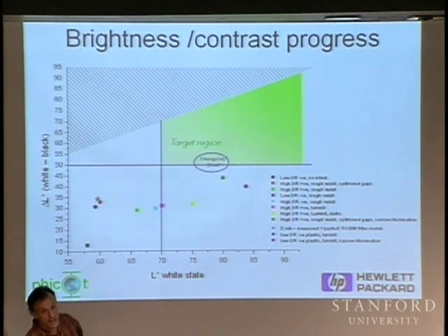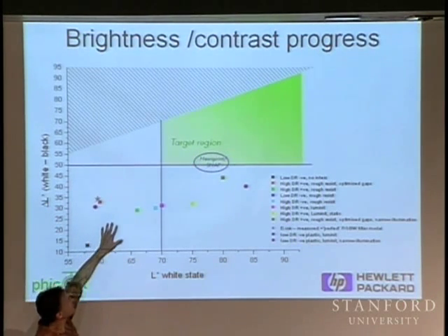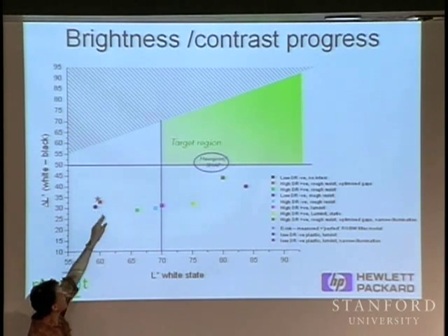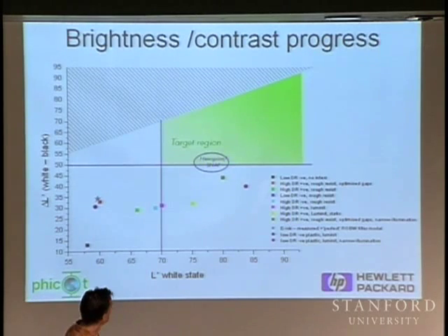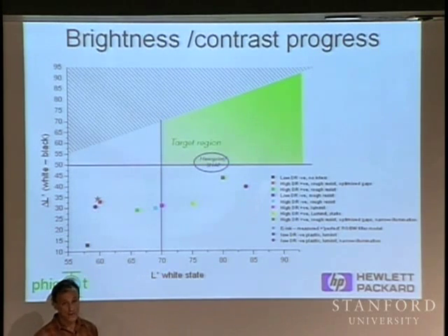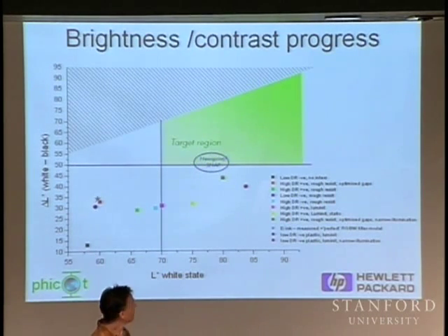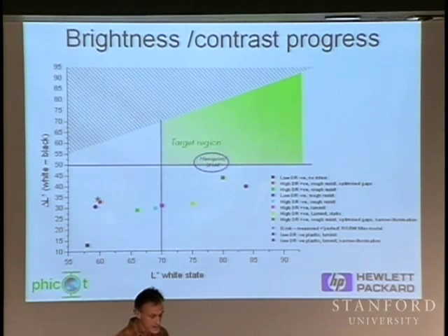That region above it is all kind of gravy. And here's kind of where some of our efforts are. And the star here is actually what happens if you put a color filter in front of e-ink. And that's going to give you, and actually almost anything else you'll see out there. There's a number of color reflective displays that have started to show up. Pixel Qi, the Flepia that's been introduced based on Kent's cholesteric LC material. And all these are going to be kind of way down this quadrant someplace. Fundamentally, any of these technologies that are basically space multiplexed color, color filter type arrangements are going to suffer from that same effect.